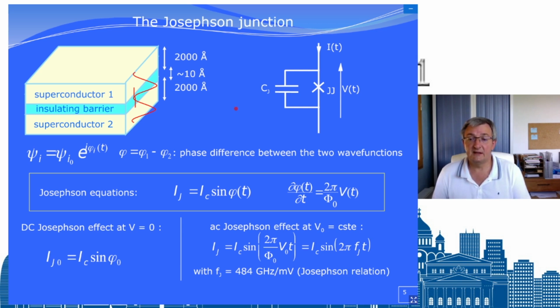And basically, if you don't pay attention, this capacitor will shunt completely your device because it has a high capacitance, and then it will shunt the high frequency signal. So even if the device can go at 700 gigahertz, the capacitor will shunt it unless you pay attention to it and you try to resonate it, at least in some frequency range.